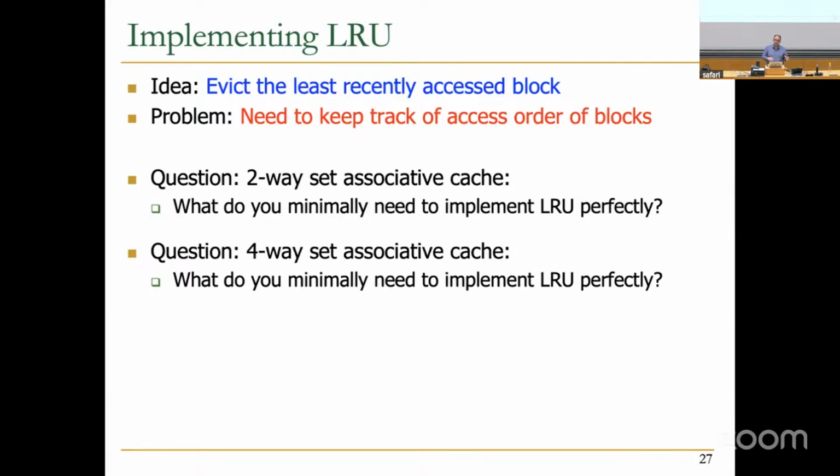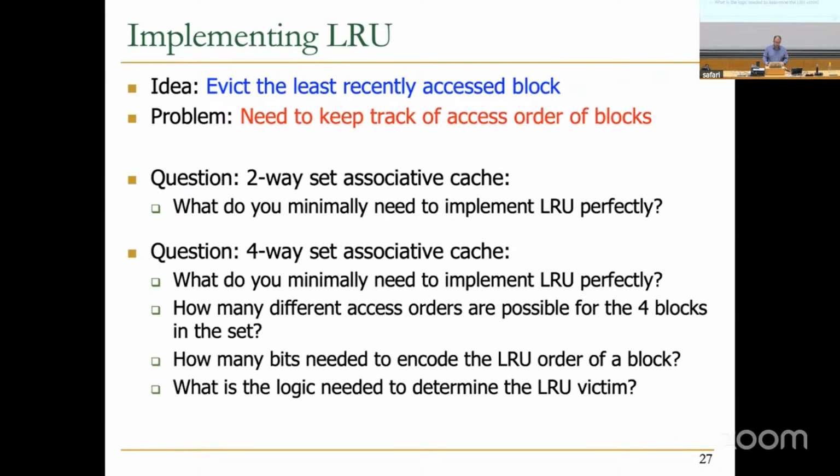But there is also another way where you store a few more bits, but that can simplify your logic. For example, if you store 8 bits, essentially you use 2 bits per block, so you have 8 bits in total, and that's an easy way of encoding. You're storing more bits, so you're paying more capacity cost, but that provides simpler decoding logic to understand what the LRU is.